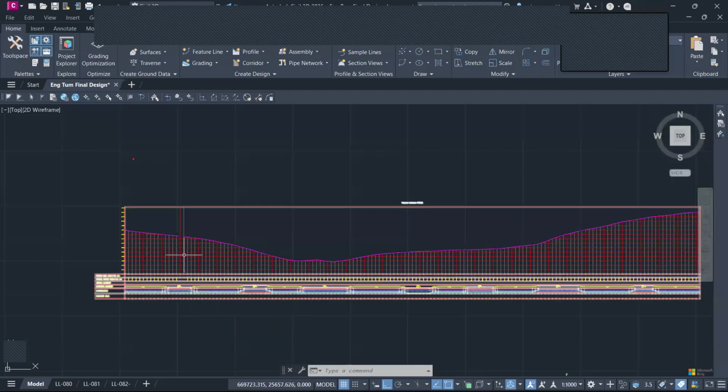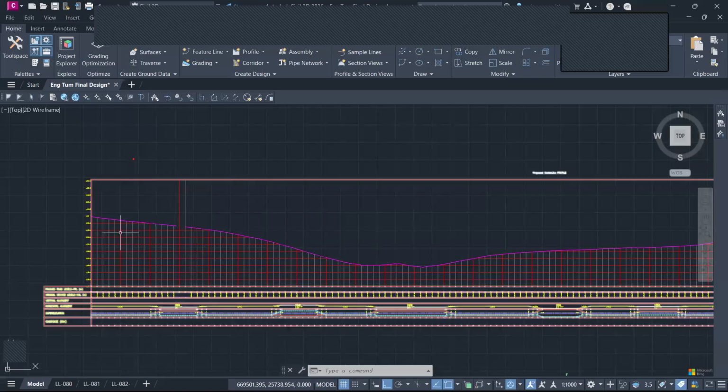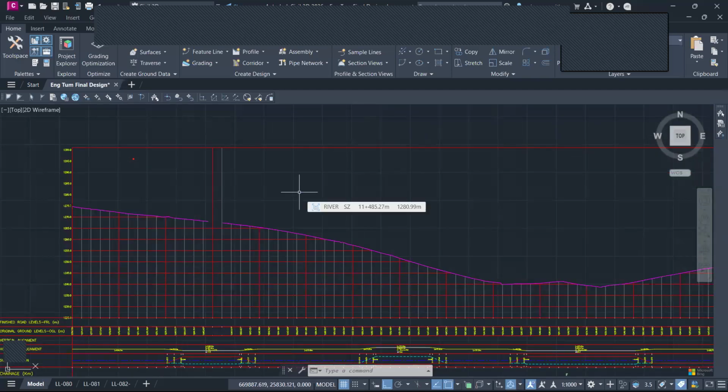So when you're designing your road profile, it is important to know that at this point, you will be designing what is called the formation level, not the finished road level. The formation level is basically where you have done your final earthworks of your section. So at that point, you'll be able to get your cut and fill. The other guiding principle is always to design as close as possible to the existing ground, because then there is the principle of value engineering.